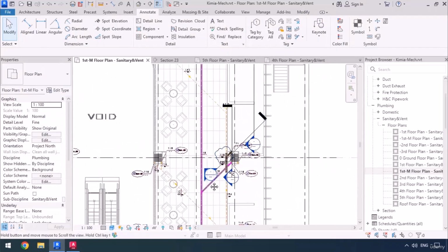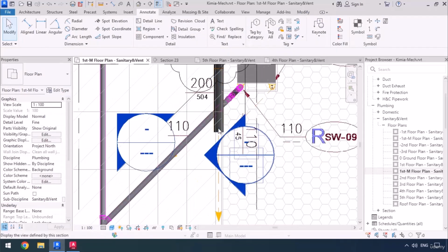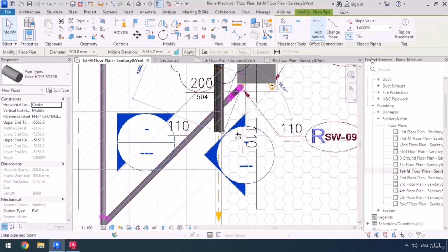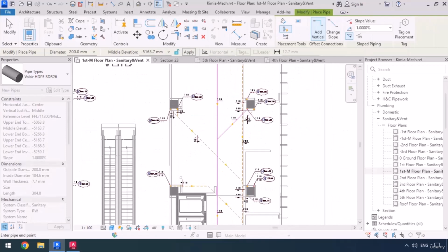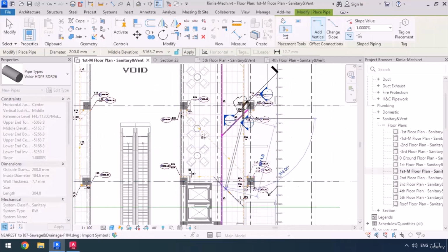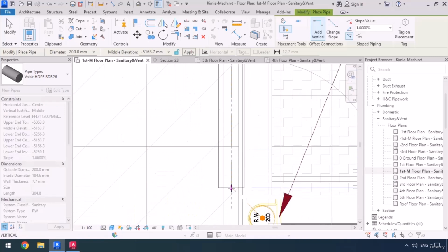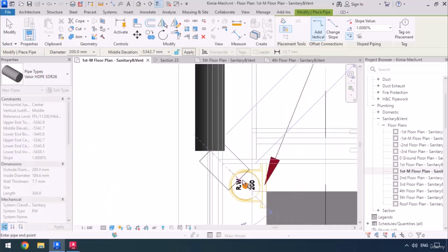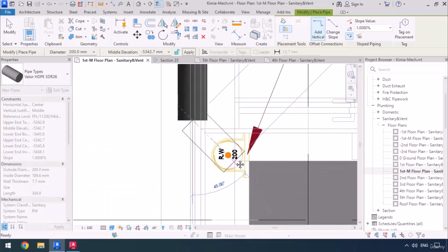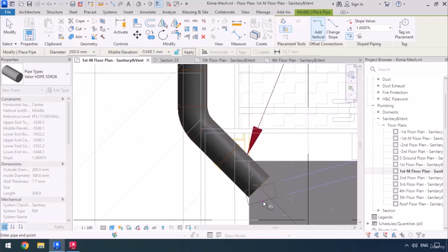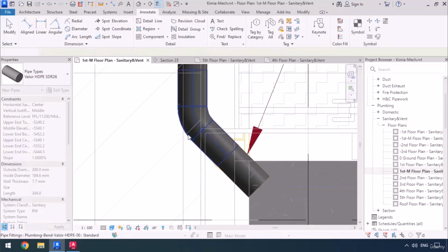Now we're going to put aside what is coming in before it. Instead, we're going to right click on this pipe, then select Draw Pipe, and we make sure the slope is down. Then we're going to draw all the way down to riser number 18, and later we're going to add these branches too. So go over here, click, then we're going to go at a 45-degree angle. Actually, let's draw the pipe even longer to make room for the elbow to be placed.